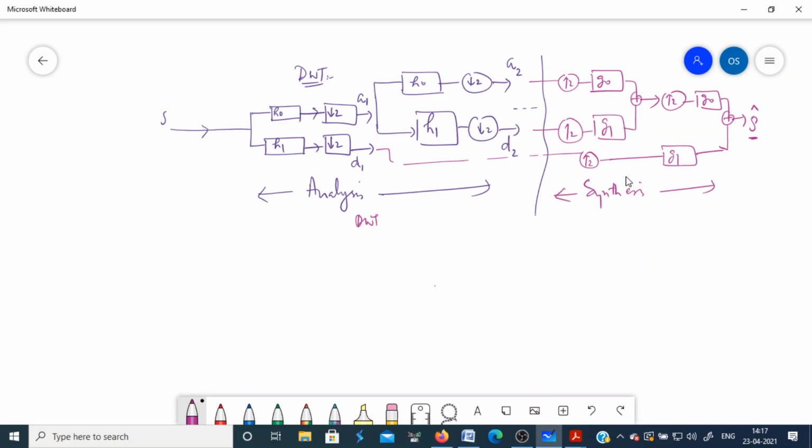or we say this is DWT and this is IDWT. Okay, so here the signal processing, or this wavelet, plays a role in between. So if you just decompose the signal into approximation and detailed coefficients up to some level, suppose n, and then you just apply the output of this analysis filter bank as input to the synthesis filter bank, your output should be exactly the same as the input, if you do not have any modification.